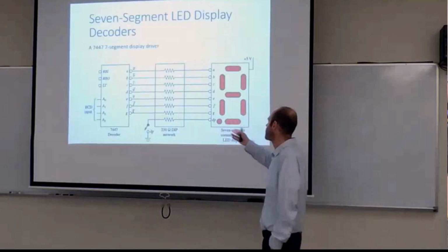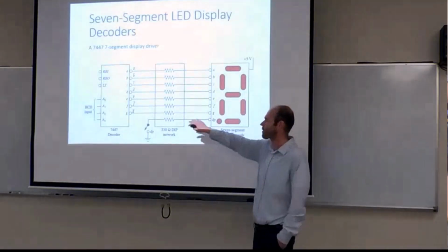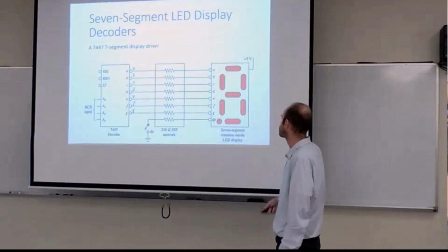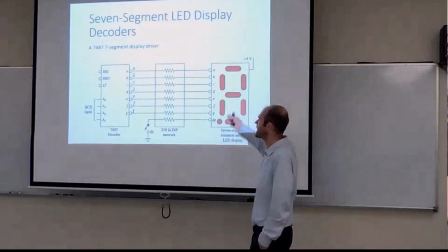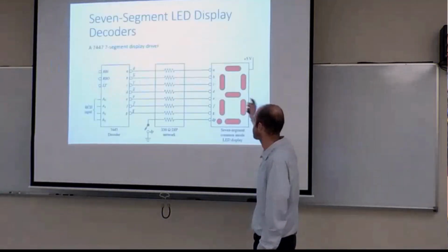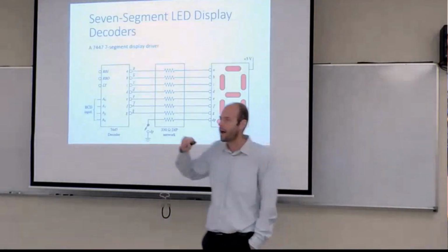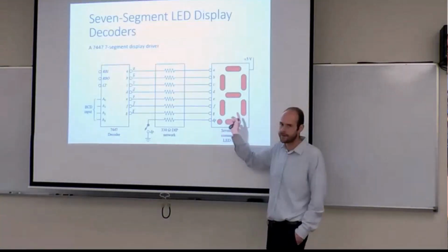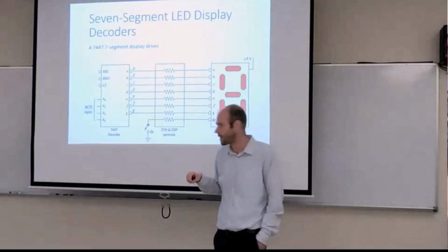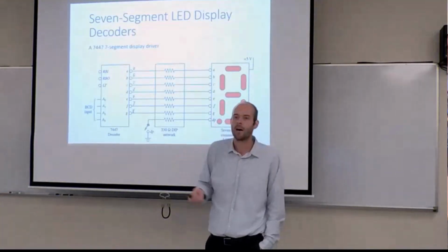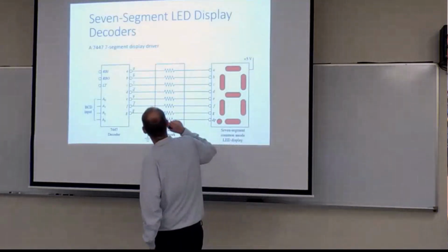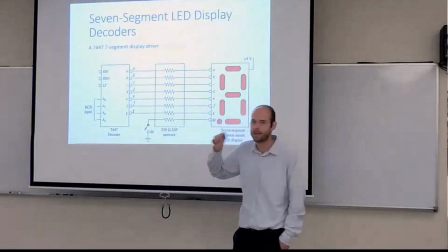But in general, these are all just LEDs, and they require resistance, of course. So we have current limiting resistors involved, and we're running LEDs to generate our 7 segments. We'll play with those a little more later on. Our lab does reference 7-segment displays as an output. For us right now, we don't have 7-segment display modules.